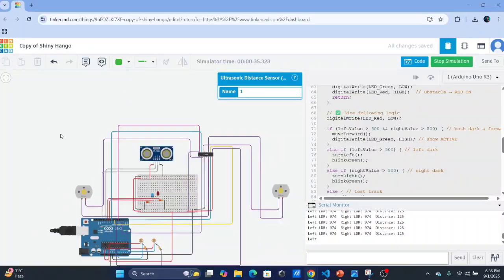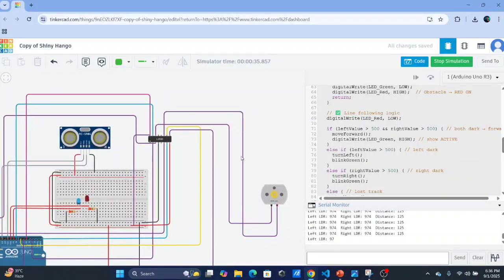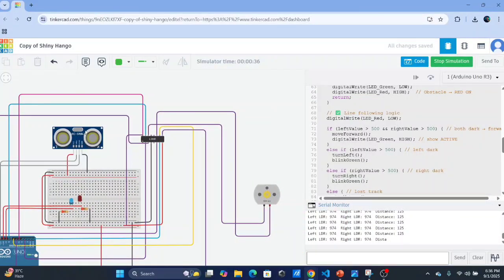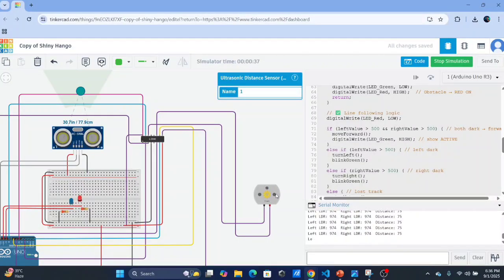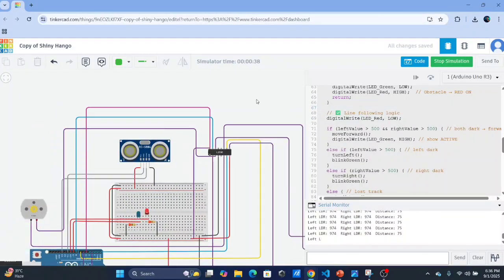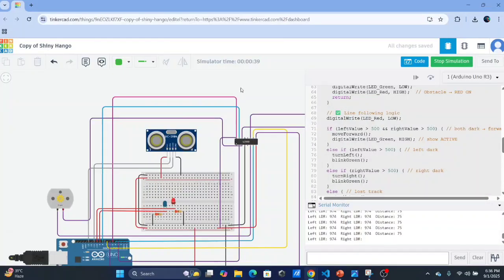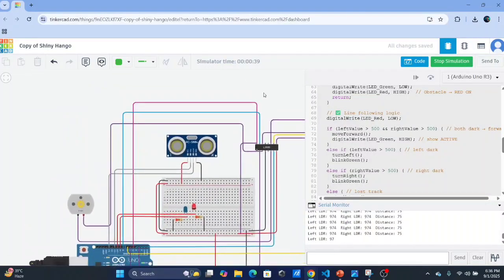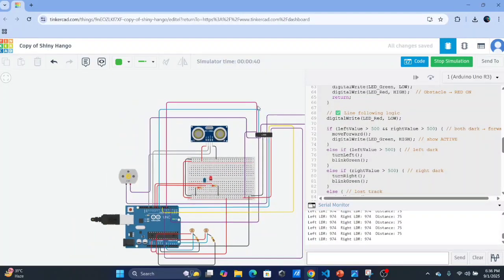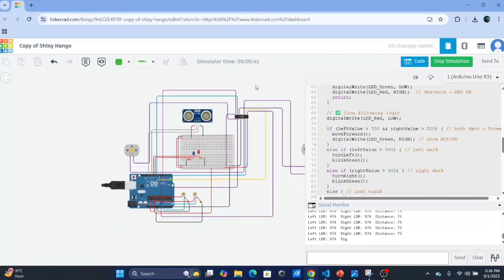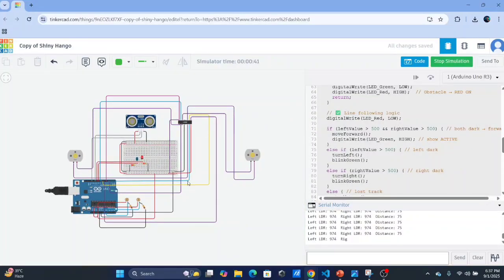And to zoom in here also, both the motors are moving, and if obstruction is detected, like this is nearer to this, both the motors stop. Second, yeah, both of them stop. So this is the simulation diagram that we have created for the robot working principle using mainly the embedded system, the microcontroller, the sensors, and the motor driver for controlling these two motors.